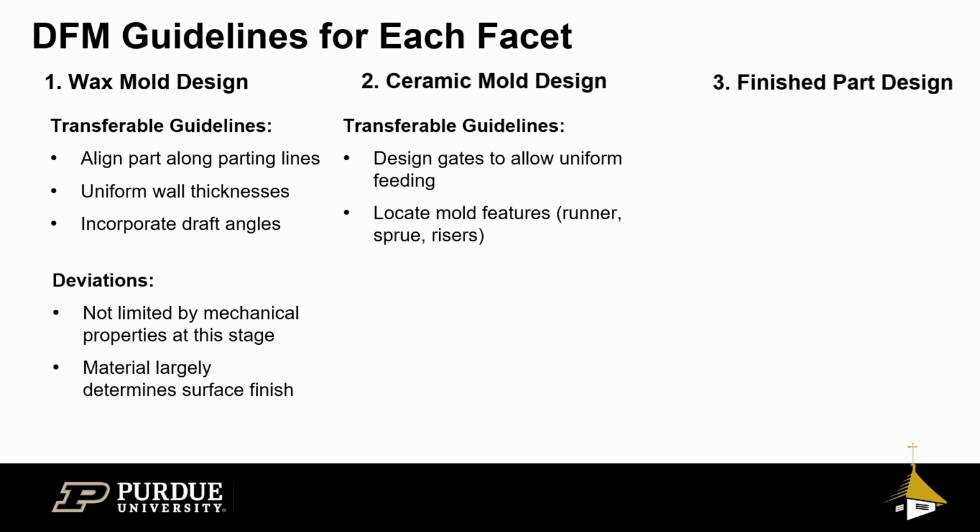Too many individual patterns may increase turbulence or risk incomplete filling in some areas. Alternatively, too few patterns will result in wasted shell volume that could have been used to make more parts per operation.